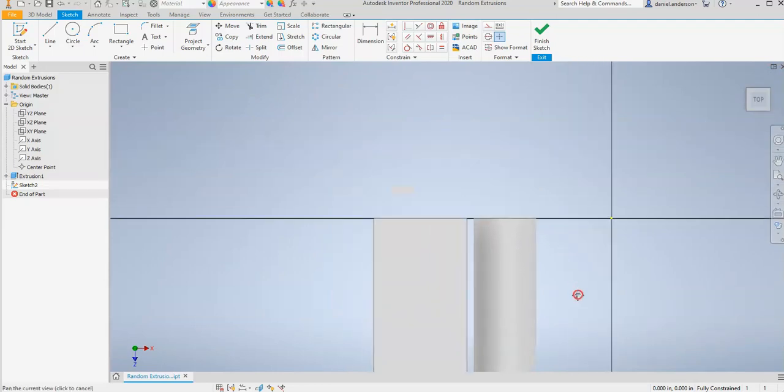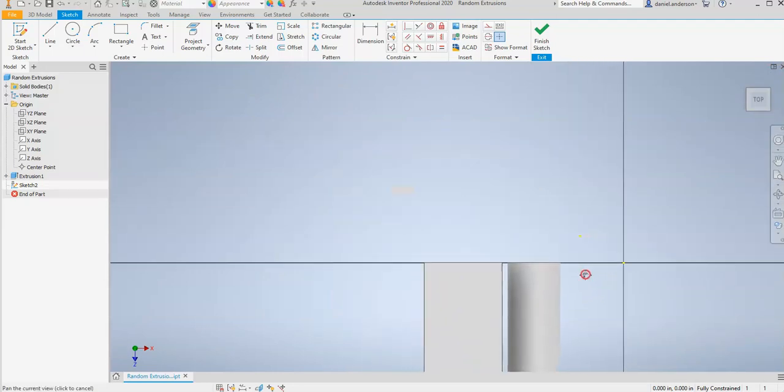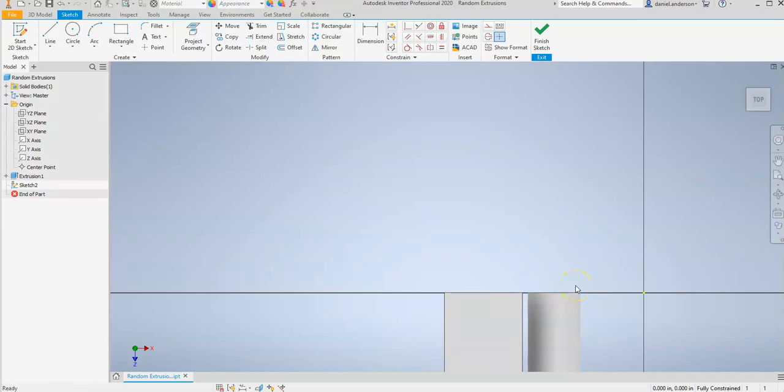And let's go to this top left corner again. So I'm going to click my scroll wheel in and move it over. And let's draw some different shapes. This time I want to click on my line tool. What I'm going to do is click and drag, but I'm going to let go of click. I don't hold click when I use my line tool. I click, let go, drag my mouse, and then I click a second time.